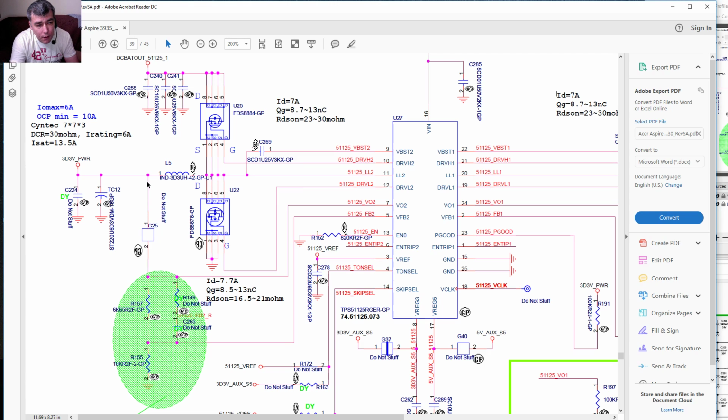And this from here, you see this is on the output, yeah? You have 2 capacitors on the ground, and you have this resistor which comes back to the chip. This is the feedback. Obviously this chip should know what happened on the output, what voltage is there, to keep the voltage stable. So that's the feedback. That's very important.